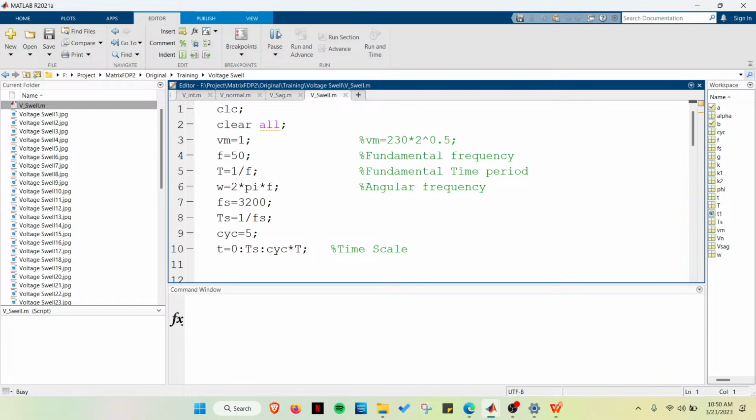See, Vinay. Generally, in an overall view, if it is a harmonic disturbance or another type of disturbance, one deep learning model can classify. If it is a harmonic disturbance, give the same signal to another deep learning model, which will again classify what different types of harmonics are occurring in the harmonic disturbance.